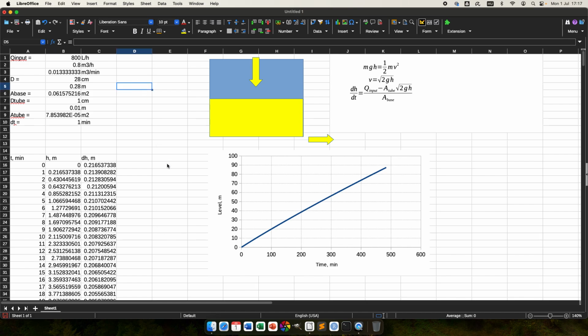Maybe we can get the upper and lower level and put a controller there. How will it work? We need limits. The controller will work with an upper limit and a lower limit. The upper limit, let it be around 2 meters, 2.3, and the lower 1.7. It will be symmetric somehow. Then I would like to decide how to operate my controller and manage the change in the filling.